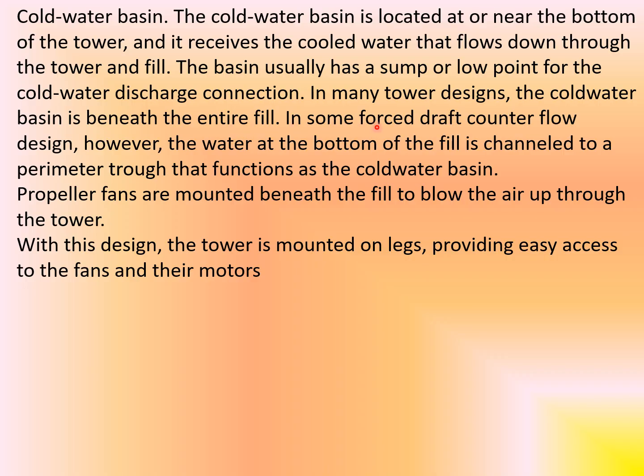In some forced draft counterflow designs, however, the water at the bottom of the fill is channeled to a perimeter trough that functions as the cold water basin. Propeller fans are mounted beneath the fill to blow the air up through tower. With this design, the tower is mounted on legs, providing easy access to the fans and to the motor.